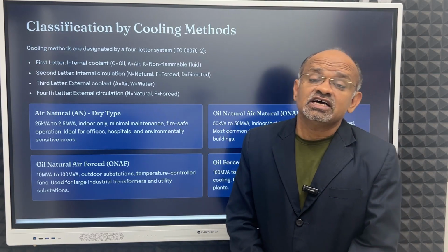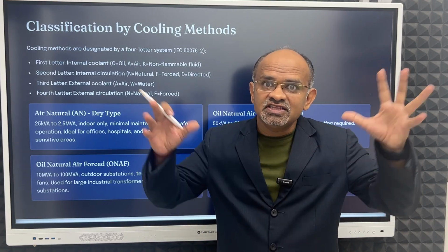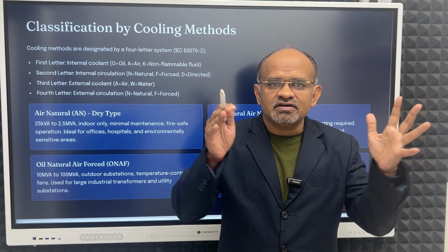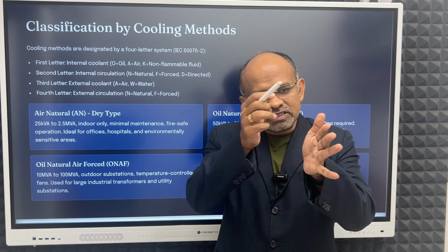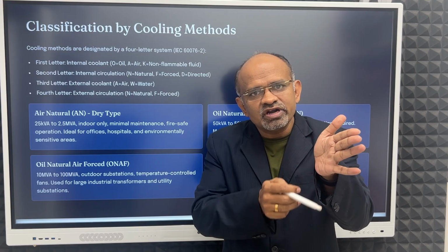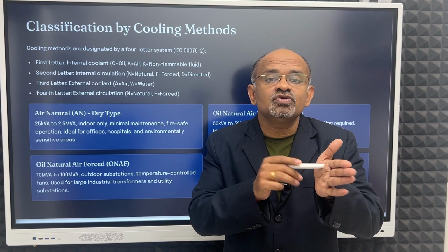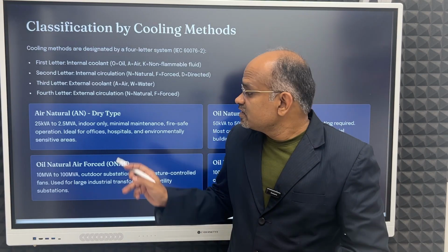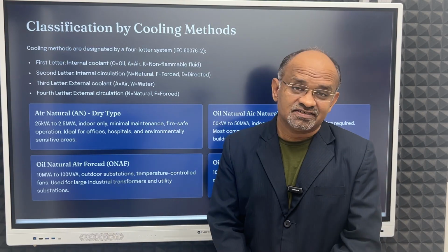For big transformers you might have seen external fans fitted on the fins. From the core of the transformer there are fins, where the oil is again getting cooled and going down. At the fins where oil is circulated, a fan is fitted, so that is called forced ventilation or circulation outside, external.